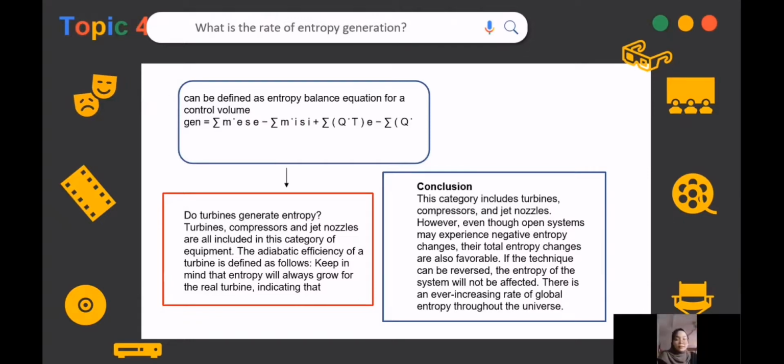A power plant's net power output is estimated by deducting the electricity consumed by auxiliaries such as fans, pumps, and flue gas treatment equipment. Mercury has an installed generation capacity of 895 MW, where capacity refers to the power plant's maximum output power under particular conditions or at full load.